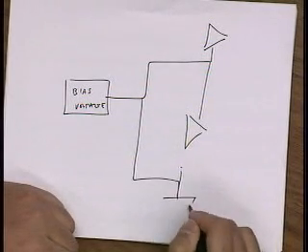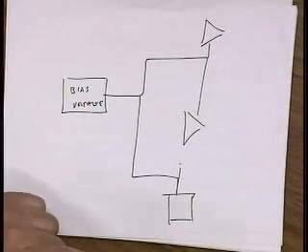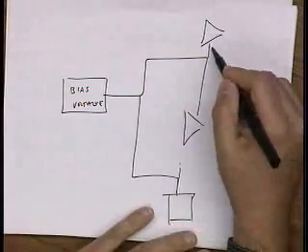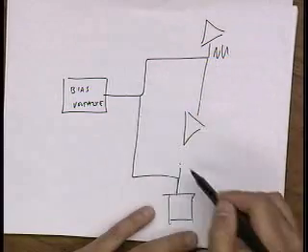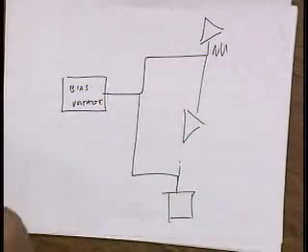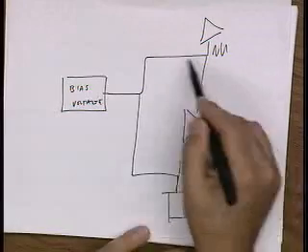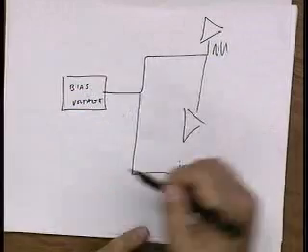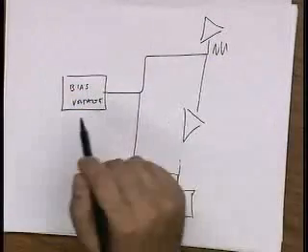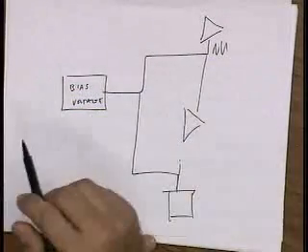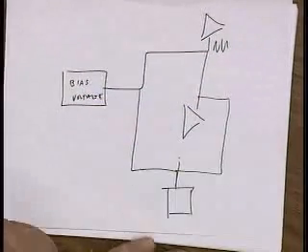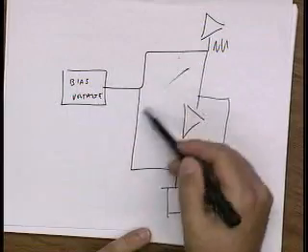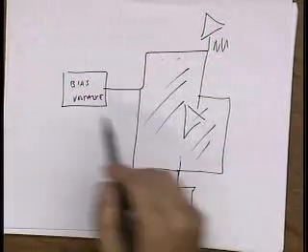Well, the issue then is that if there's any kind of noise on this pickup here, it's going to basically route that noise to every other circuit, right? And these wires, if they become quite large, they actually become good receptors of noise. So they pick up noise, especially if we're not careful and we unintentionally introduce a loop in our layout. So then now magnetic flux gets picked up here and can generate noise.